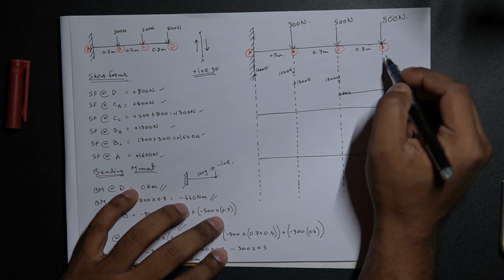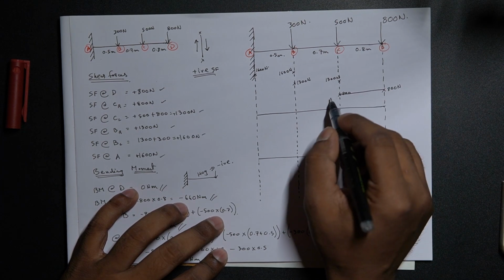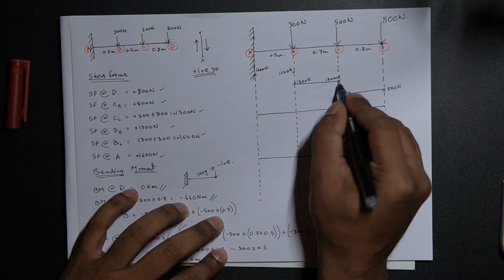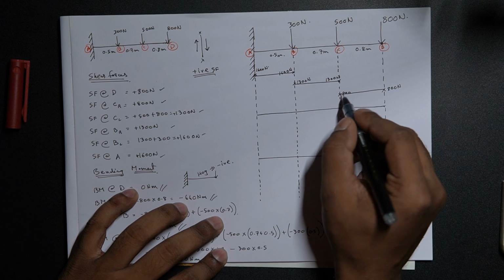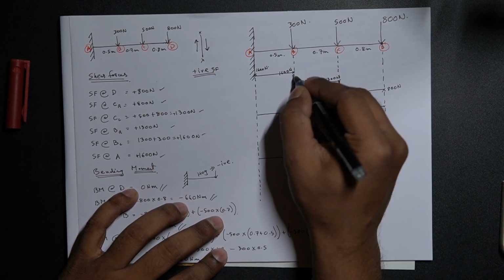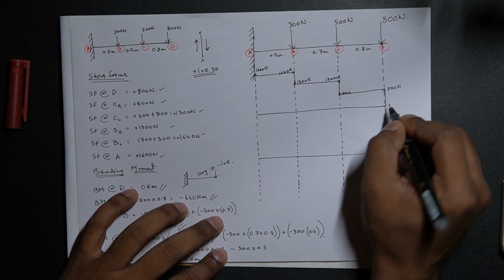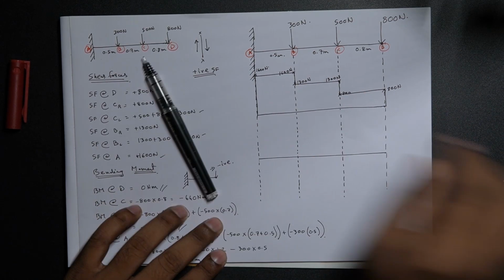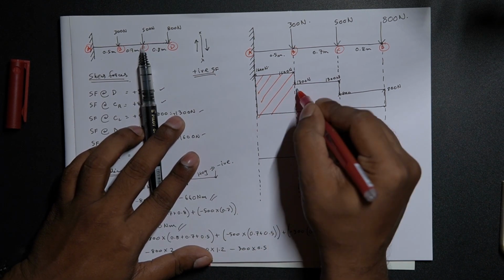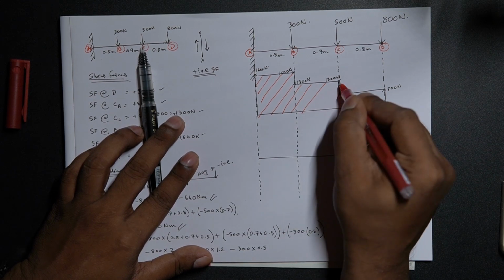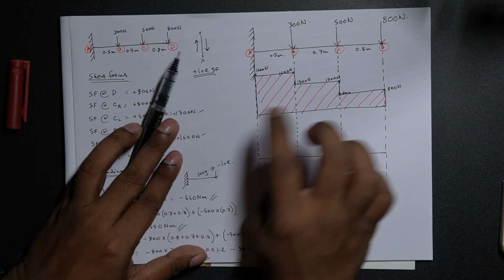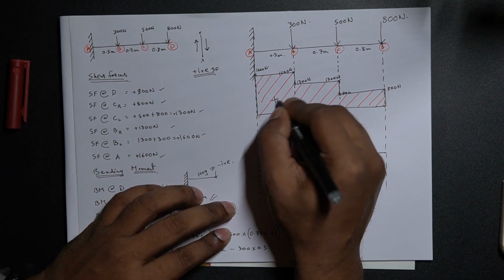Since point loads on a cantilever beam will give you a constant representation on the graphical part. The shear force for a point load will be constant, so there will be no inclination of lines or any of such. It's all straight lines. So you just hatch that. So this is your shear force diagram. It is positive.